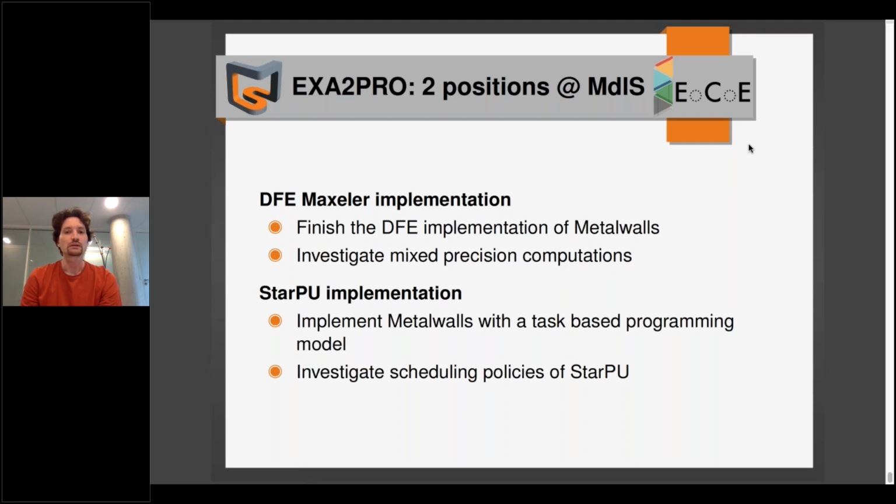But even more, you are not forced to use only single precision or double precision like on CPU. You can decide the precision you want. You can say, okay, I want 17 bits for the mantissa and 3 bits for the exponent. That's completely possible in FPGA, and then you will use even fewer DSPs.